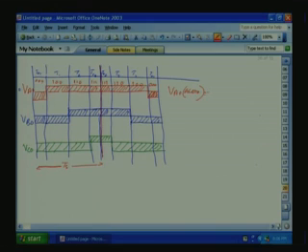That is equal to, see, either positive or negative, the amplitude is VDC by 2. So, average value you have to divide by TS into, see, during the T0, first T0 period. So, T0 periods are equal. So, we will make it the duration T0 by 2.